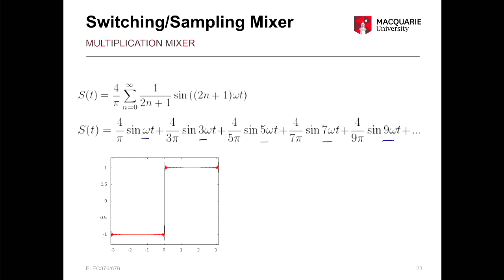You can use a mechanical relay if it operates at such a high frequency, but usually it doesn't. Relays operate in seconds or milliseconds, but when you look at megahertz, you want something operating in microseconds. So you use some high frequency electronics. There are plenty of devices that can do it. Anything with a controllable voltage or current, like BJTs, MOSFETs, or power MOSFETs. So quite a lot of devices there.